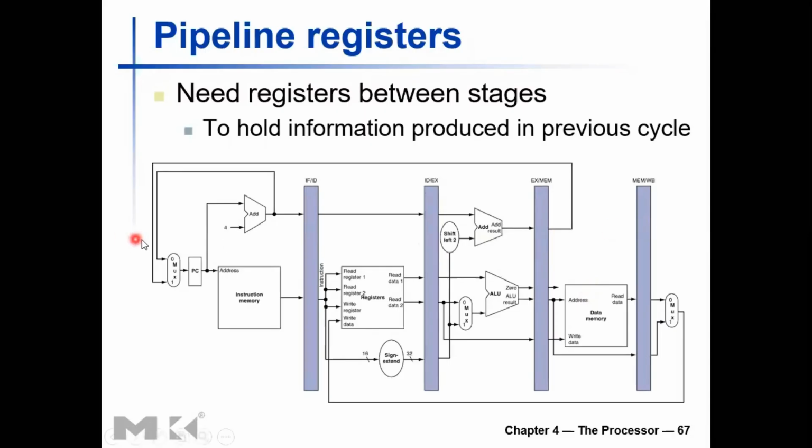So before this instruction fetch stage, you have the memory, write back, and write back and instruction fetch. You see, you are not having a pipeline register, but you are still updating some state. You're updating either the register file or the program counter based on what you have done so far in the previous instruction.